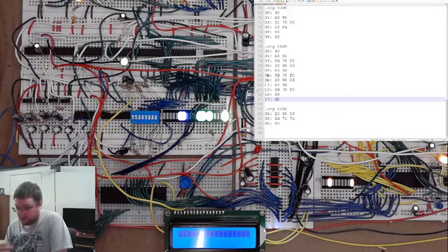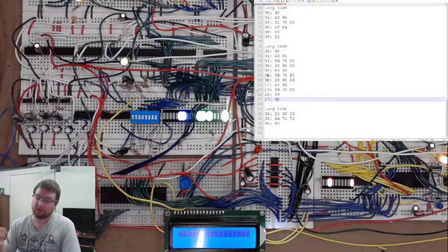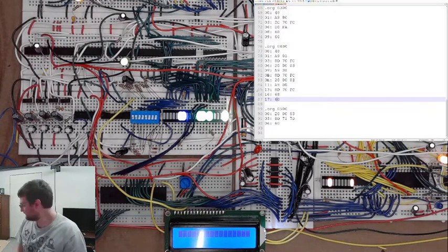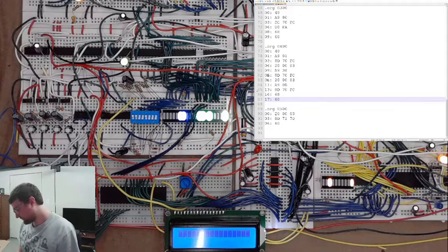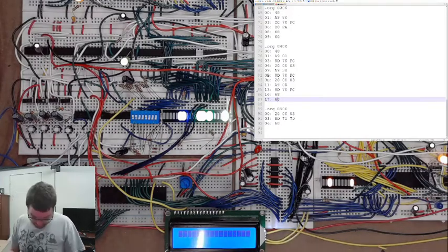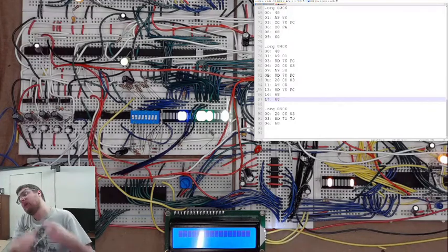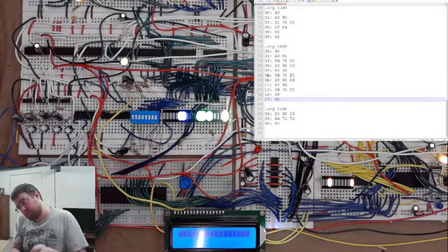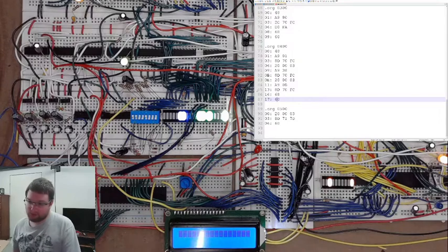Anyways, it's all a little complex. And so we need to write a very special function to be able to transfer and write to EEPROM. And that way the device can write to itself. And then we can prototype in RAM and then copy to EEPROM, which will be good. Because then I can save my work.